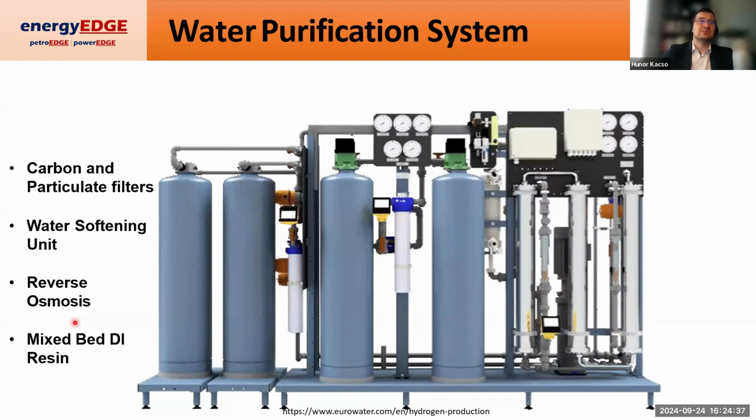Less than 1 microsiemens per centimeter would be fantastic. Even 0.5 microsiemens per centimeter is completely achievable. If you were to run the stack at 5 microsiemens per centimeter, it will come to end of life very shortly. Trust me.